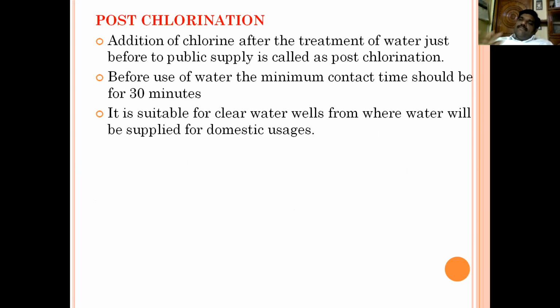Post-chlorination means that after complete treatment, the chlorine will be added, before supply of water to the public. That is called post-chlorination. Normally, the minimum contact time should be 30 minutes. For clear water wells, it is suitable, from where the water will be supplied for domestic usages.